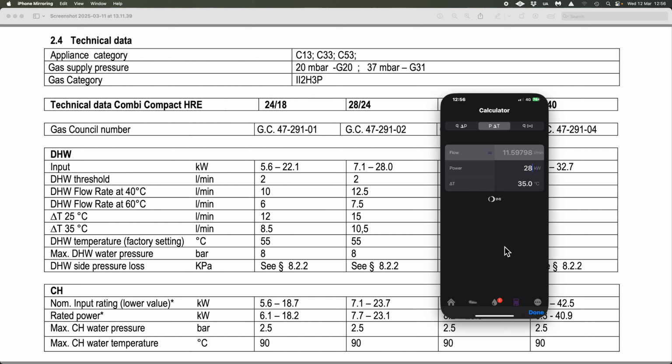But again, let's have a look, and this is why I said you shouldn't be trying to get more than around 24 kilowatts down 15 millimeter pipework. And let's all agree that most combination boilers in the UK, not sure about overseas, or they certainly are in Canada, will have a 15 millimeter or half-inch inlet and outlet to the actual boilers themselves. So let's have a look at what pipework it's saying for that and make a decision.